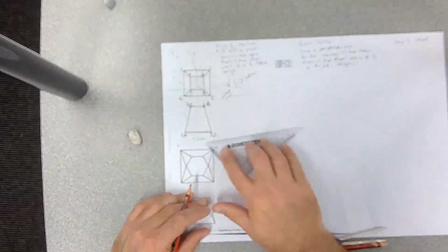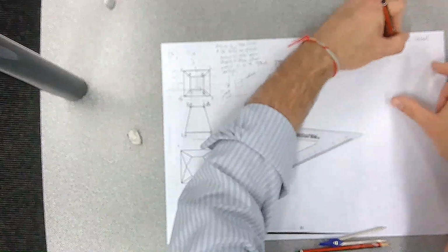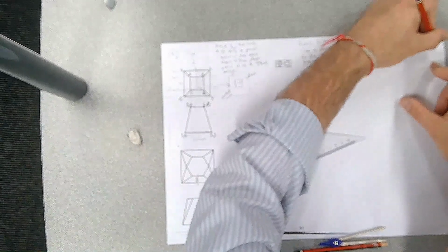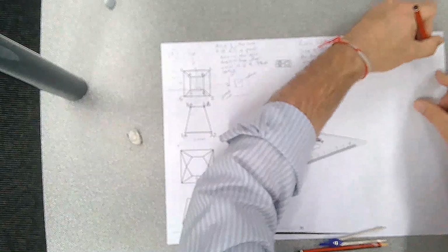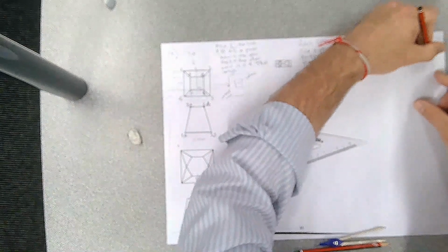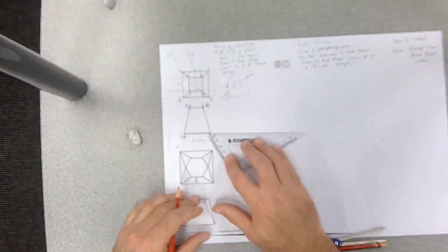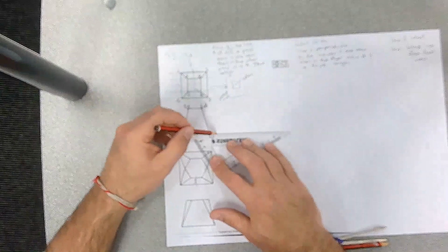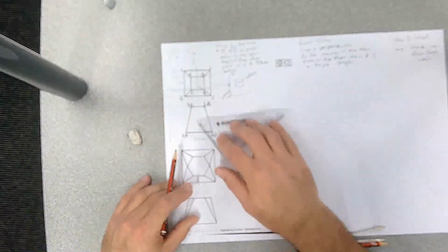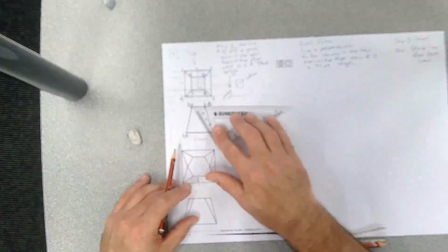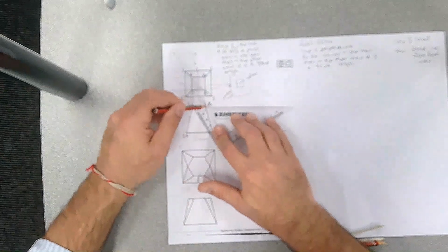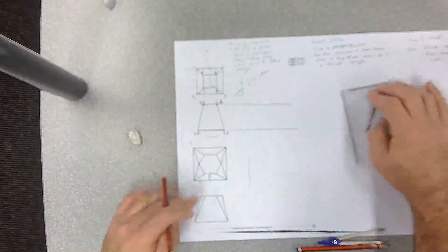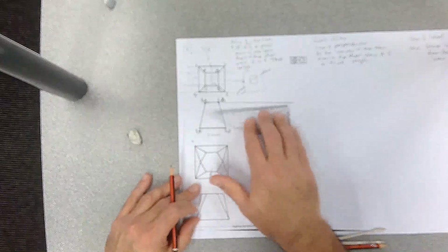Once you've done that, step 2 is extend lines from front view. And we've done this in our previous example too. So we just pick our bottom line and we draw a line out, and then we pick our top view and we do the same, line out. You can see on this page that I haven't quite got my drawing straight, so just make sure that you line up those lines with the bottom and the top.